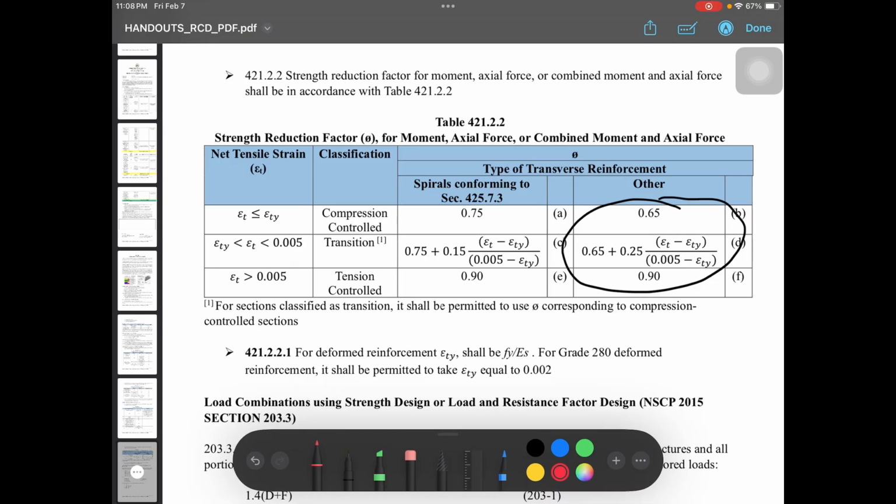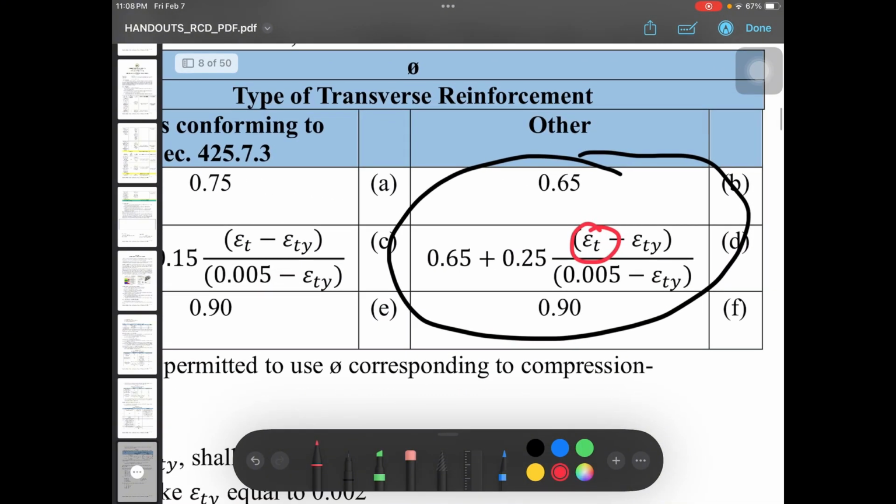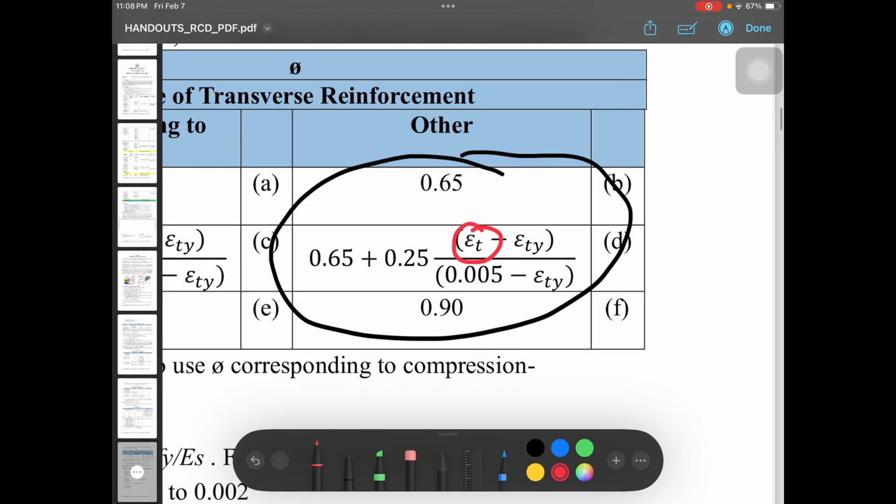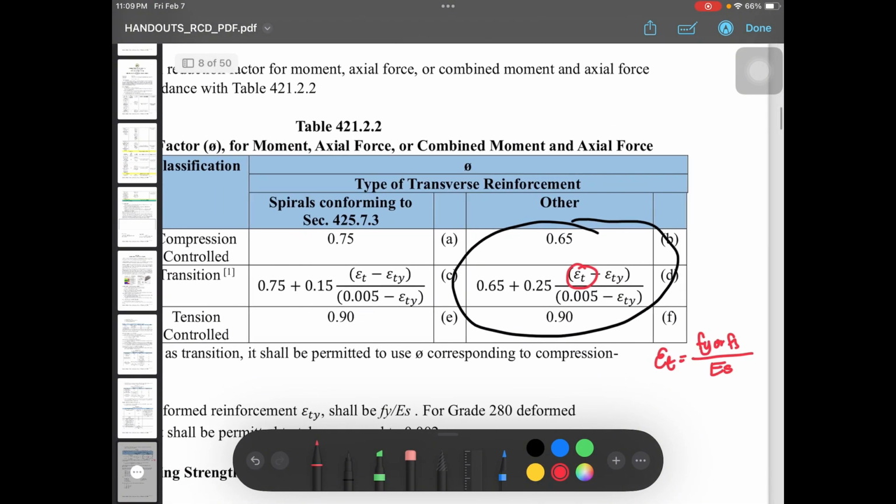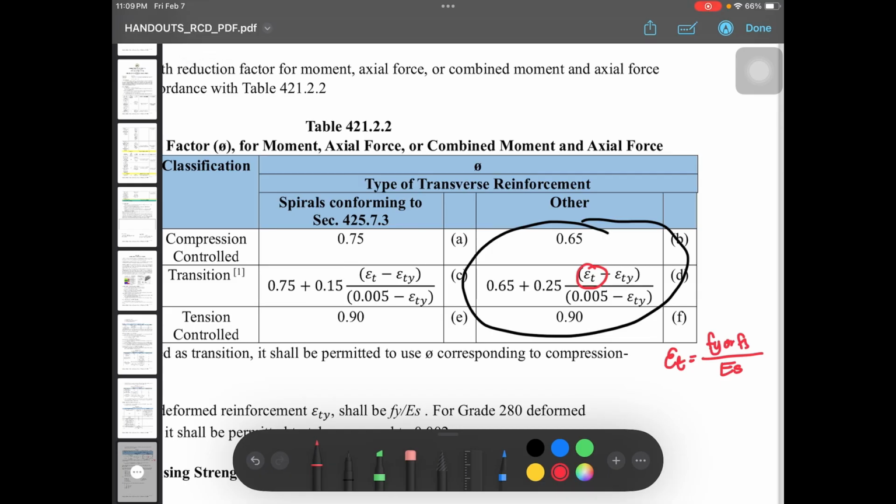The main difference in the equation is that it considers the strain of the section, while what we used earlier is the tensile strength. But they are the same, since strain is the ratio of the normal stress, or Fs, over the modulus of elasticity of steel.